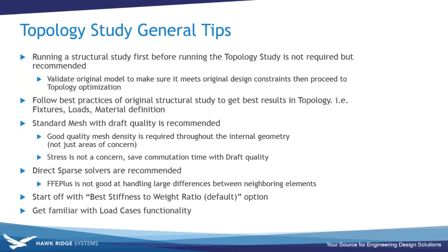In a regular stress test, we may add a mesh control or say that I want to refine the mesh in a certain area, which may be my concern. But in this case, we just need a good quality mesh throughout the entire geometry, inside and out. So a standard mesh can do that for us.